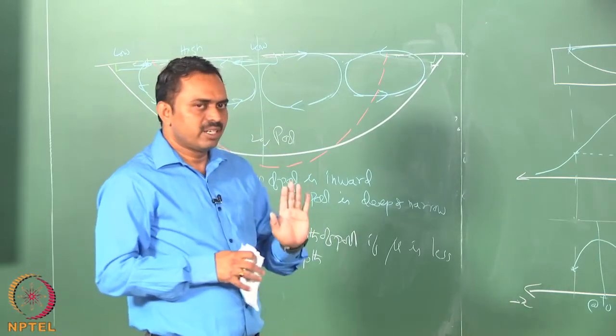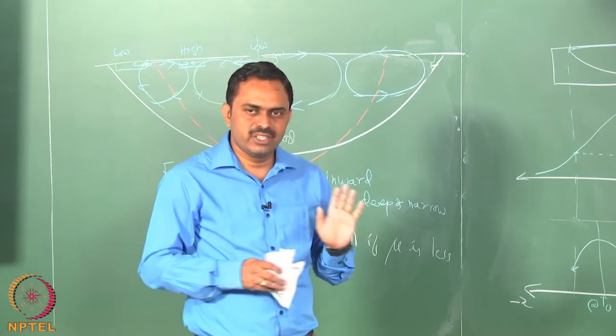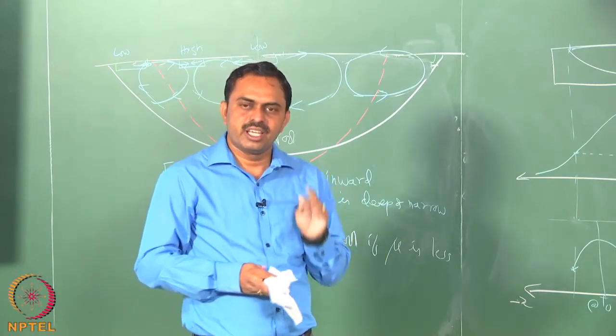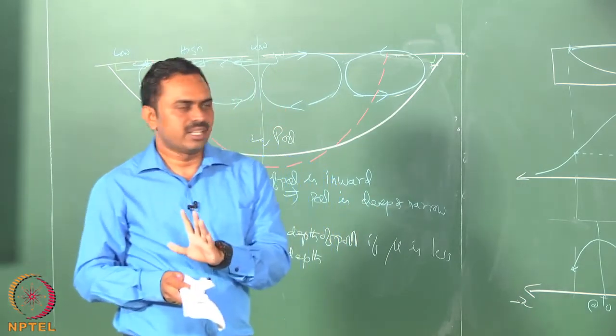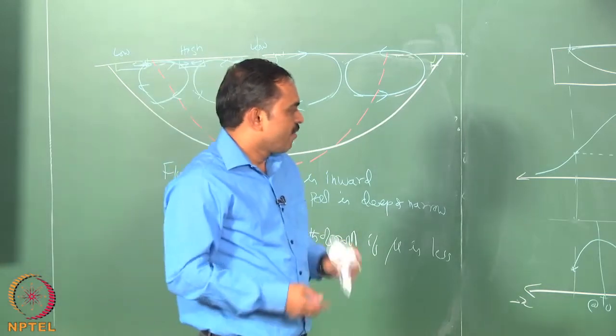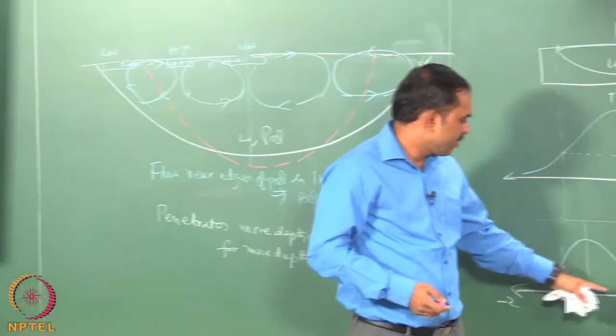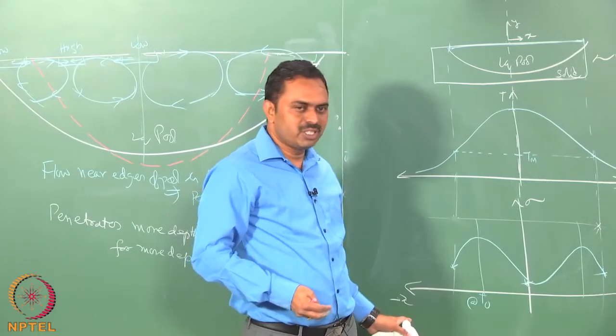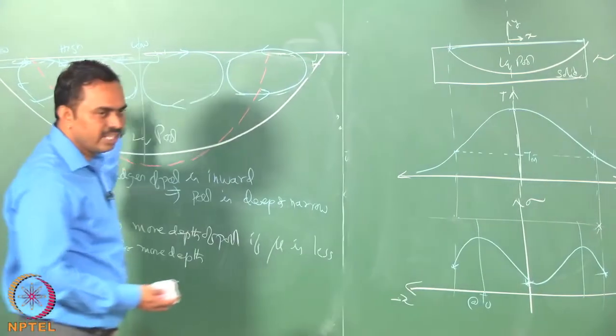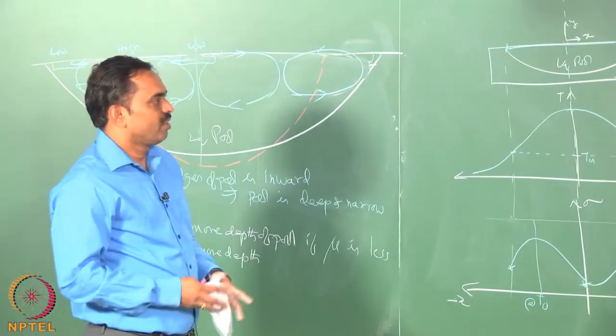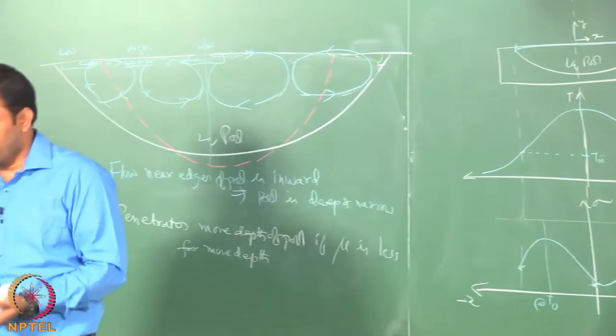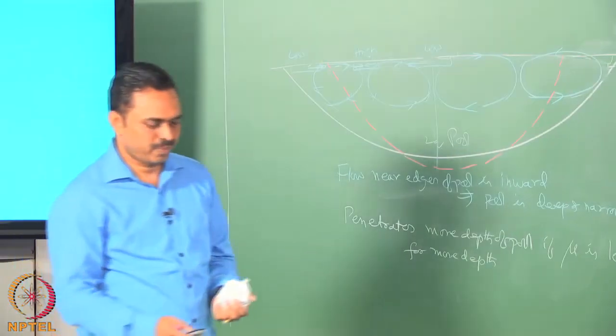So, one has to always pay attention to how the surface tension is changing as a function of composition, if composition is changing as a function of distance. Ultimately we have to inspect whether surface tension is changing as a function of distance. The moment it changes, you immediately start seeing flow because of that variation. This is how the Solutal Marangoni convection plays a role.